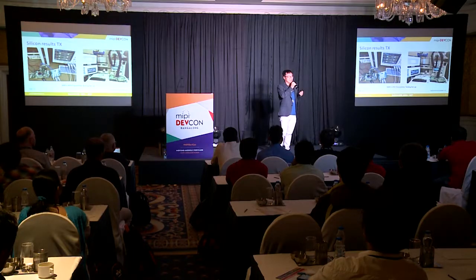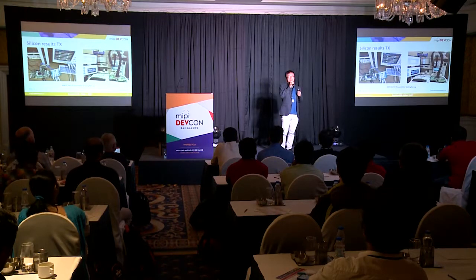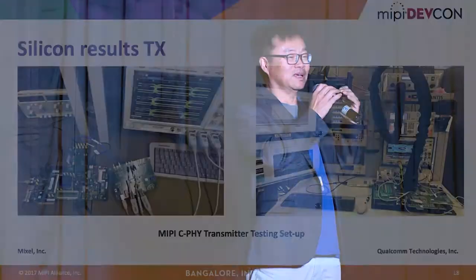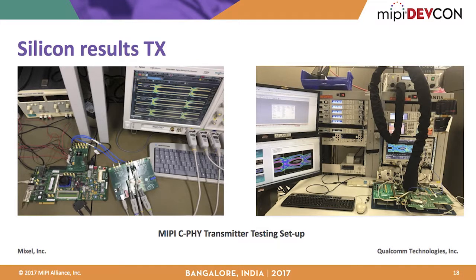So on the design side, maybe there's some challenge to have both designs compact, but the challenge is more on silicon validation, more on the PCB design side, actually. Like you say, one is differential and the other one is pseudo differential. I don't want to say it's fully single-ended, but it's a differential because the return current is coming back, but it's pseudo differential. So, 2 and 3 have no easy common denominator. It's hard to find.